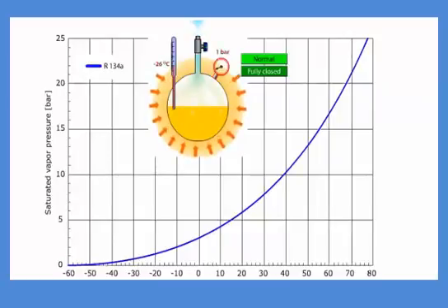When the pressure in the flask rises, the evaporation temperature will also rise because there is coherence between the pressure and the saturation temperature, which is what the curves show. When the evaporation temperature has reached the ambient temperature surrounding the flask, the heat energy transmission will stop, hence the pressure will stop rising. The end pressure can be found on the y-axis of the curve. When the outlet is opened again, the evaporation process will start up again with increasing intensity as the pressure drops.